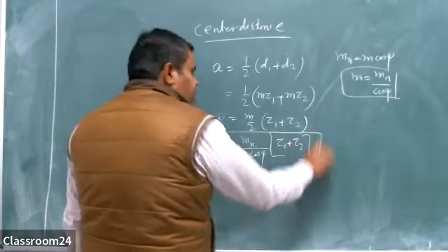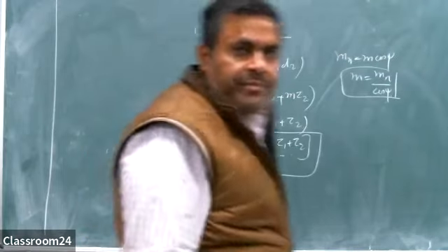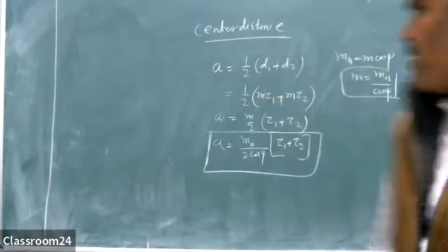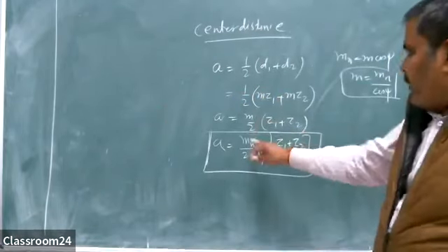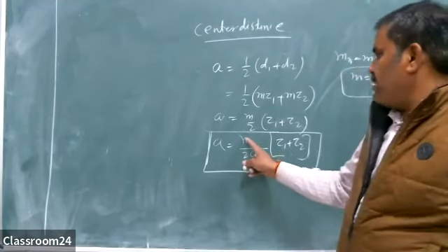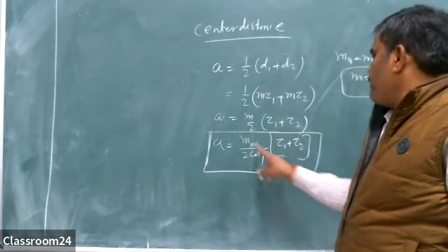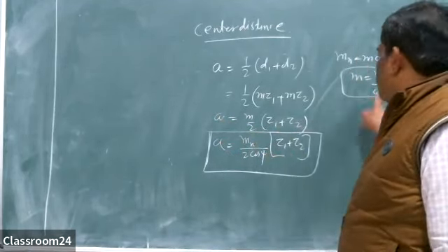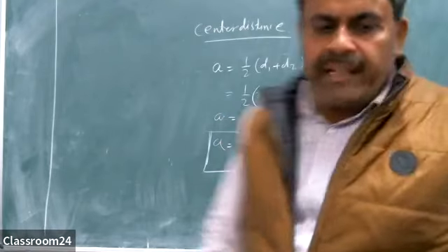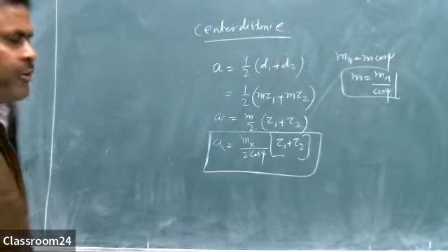This is the center distance between the helical gears. Very simple. Just use the relationship, because in numericals the normal module is calculated, so normal module is available. That's why the formula has been developed in the form of normal module. And the relationship is m equal to mn by cos psi. So I think this formula is clear to you.